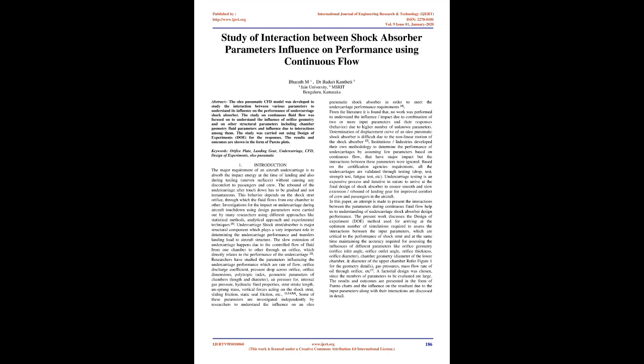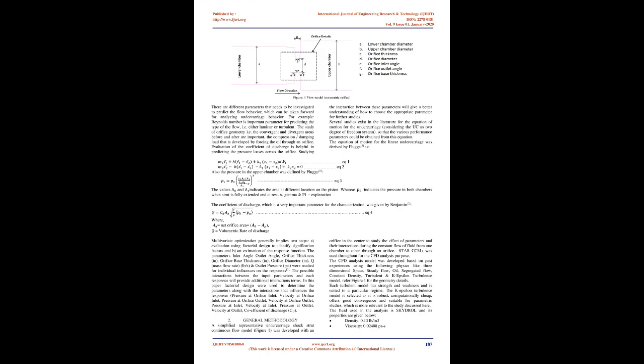[4]. From the literature it is found that no work was performed to understand the influence/impact due to combination of two or more input parameters and their responses, behavior, due to higher number of unknown parameters. Determination of displacement curve of an oleo pneumatic shock absorber is difficult due to the nonlinear motion of the shock absorber too. Institutions/industries developed their own methodology to determine the performance of undercarriages by assuming few parameters based on continuous flow, that have major impact, but the interactions between these parameters were ignored.